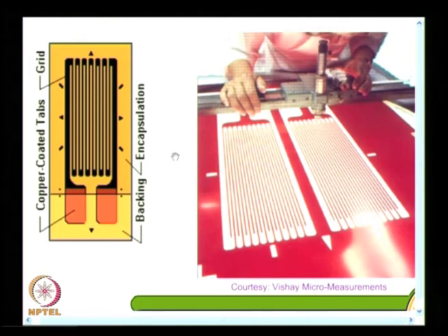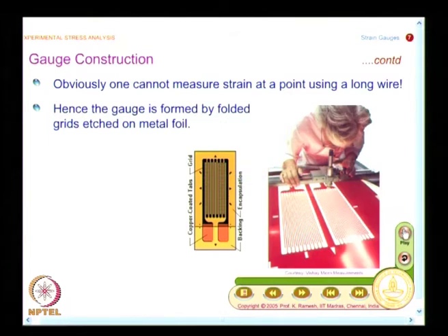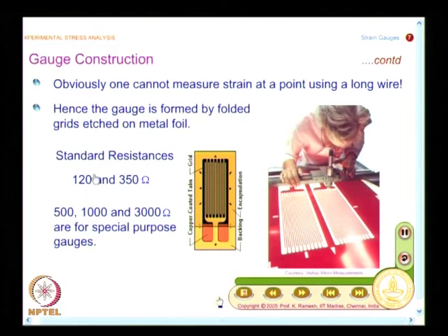And we will now see what are all the resistances that are available. So, you do not have it as 100 ohms, the base is 120 ohms. This is from measurement consideration. For our discussion, to alert that you need a long wire, I said let us start with 100 ohms, but the least resistance that is commercially available now is 120 ohms.